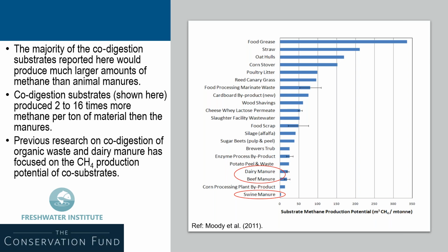Co-digestion can help balance factors that control anaerobic digestion, like ammonia concentrations, carbon-nitrogen ratios, pH, volatile solids content, and volatile fatty acid content. Let's take aquaculture waste, for example. Aquaculture waste solids tend to have a C:N ratio that is below the optimal range for the anaerobic digestion process, and it could have a detrimental effect on methane production, which in turn can reduce the energy content of the biogas. In such a case, co-digestion of other organic substrates with a high C:N ratio with the aquaculture waste may be an effective way to enhance methane production and improve energy generation by balancing the C:N ratio.